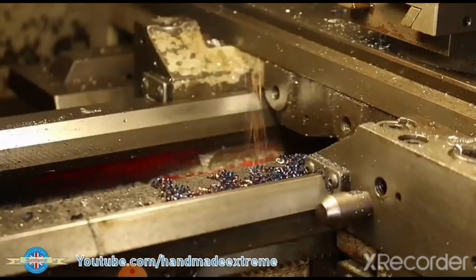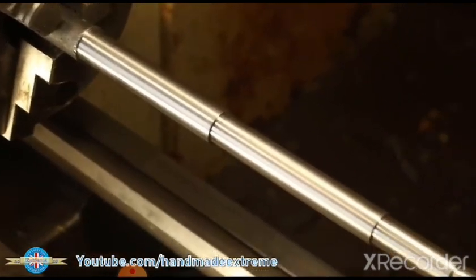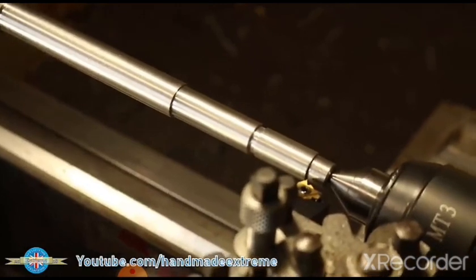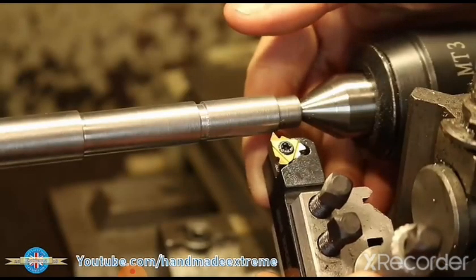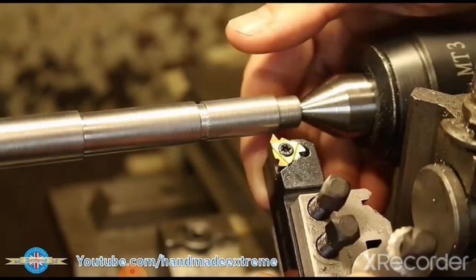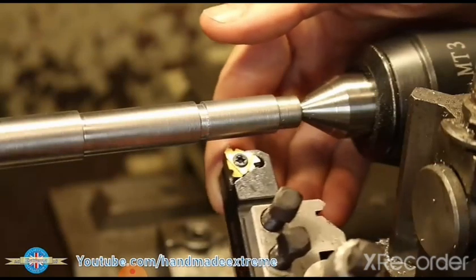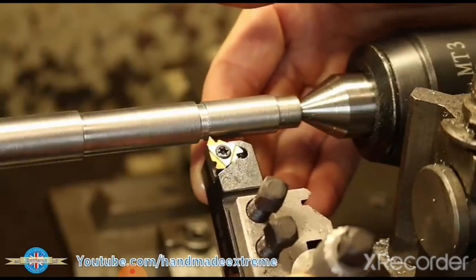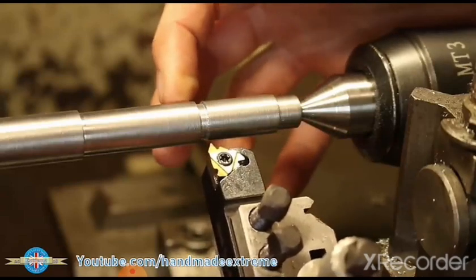I started by getting the shaft roughly to size before cutting the threads. So I've got my shaft turned down to its final dimensions, and we're going to cut a thread on this end here. We're going to cut a 60-degree thread, which is metric. This little tool here has an angle on the end of it that's 60 degrees, so the tool shape defines the teeth on the thread. I've cut a little groove in just here so that when I'm bringing the tool across, I've got a little safe space where I can stop the tool before it runs into this next feature.